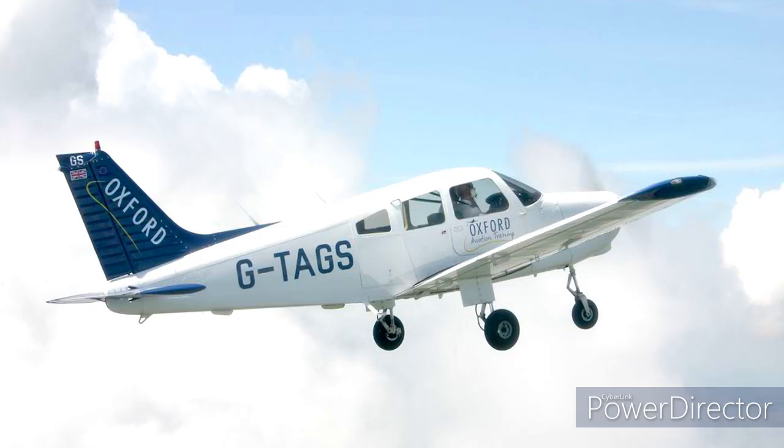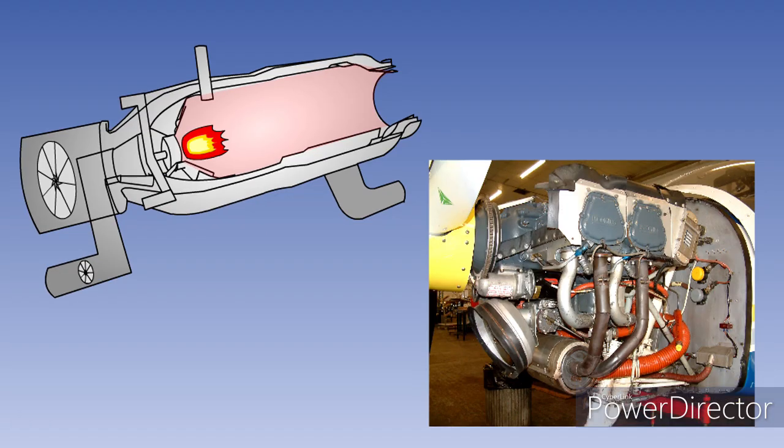First, we will look at the ram air systems used in light aircraft. Outside air is introduced to the cabin through forward-facing air intakes. Some of this ram air can be heated by an exhaust gas heater or a combustion heater, and then mixed with the cold ambient air in varying proportions to give a comfortable cabin temperature.